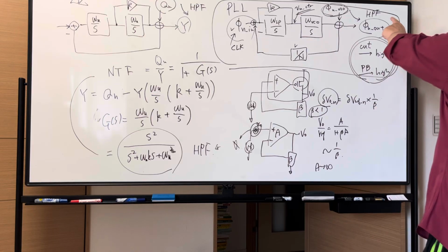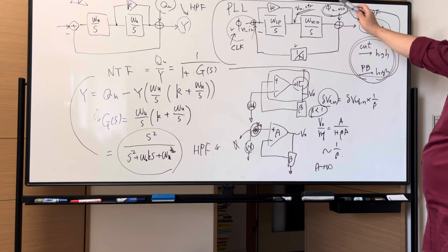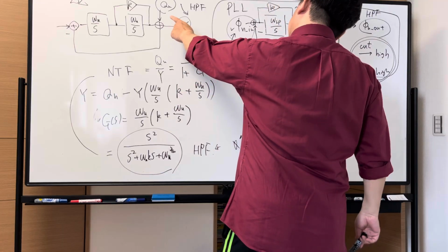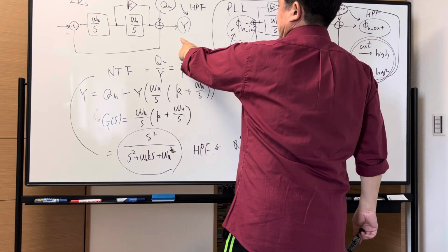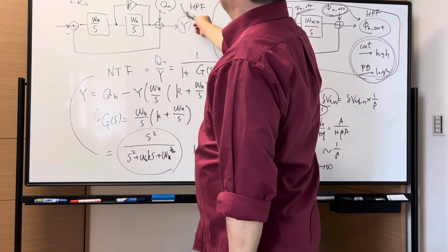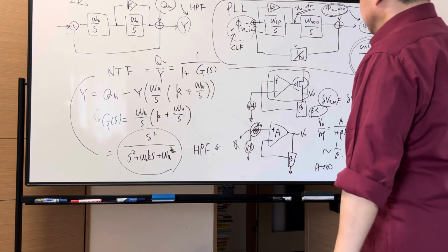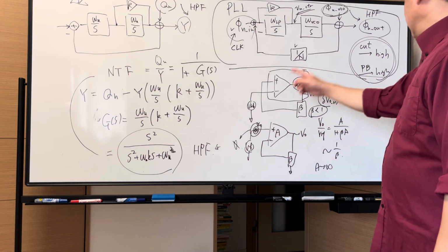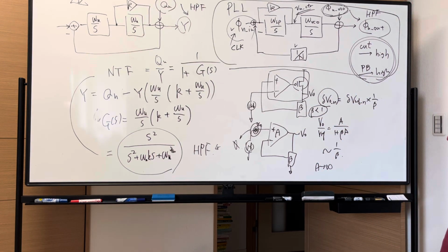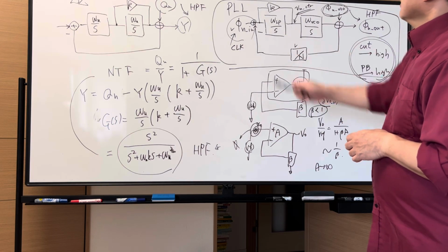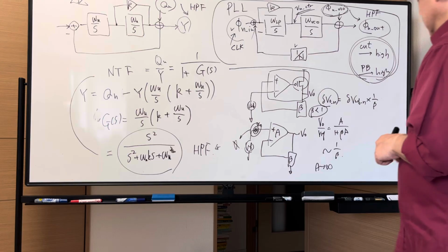The PLL is a high pass filter for VCO phase noise to output phase noise, like the quantization noise to output noise transfer function constitutes a high pass filter for a delta sigma modulator. And this is just a story for a linear regulator, LDO. If possibly we can have a noiseless voltage difference, it's the best. And also it follows by the PLL cases.